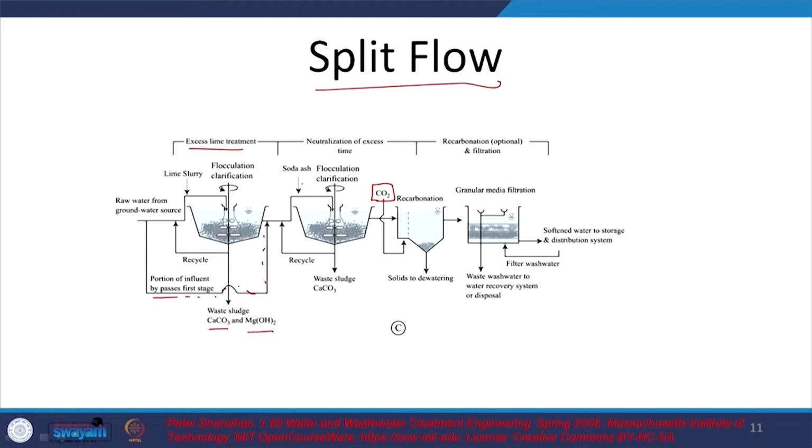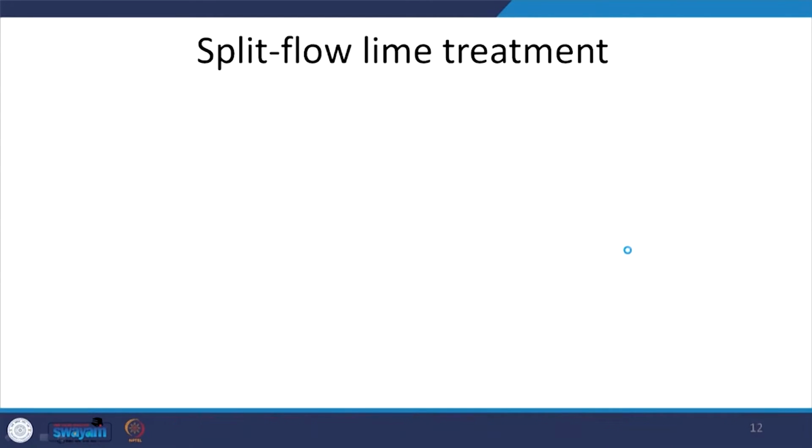And then I come out here, I want to bring the pH down. So, I added carbon dioxide in the previous case, but here I am going to use the bypass or the raw water here. So, that is something to keep in mind. So, pH down, and also if there is enough carbonate in the relevant raw water, that will also add to the relevant alkalinity or the CO3²⁻, and for the additional required you are going to use soda ash. And then the carbonates. So, assuming that the pH is maintained at the right condition, CaCO3 is going to precipitate out. So, after this stage you have a pH of 10.5, pardon me. So, carbon dioxide is going to be used to bring down the pH to acceptable levels of 8 or 7.5. So, split flow, that is the major aspect, but simultaneously you can have other systems like RO or ultrafiltration and such. I believe we are discussing that now.